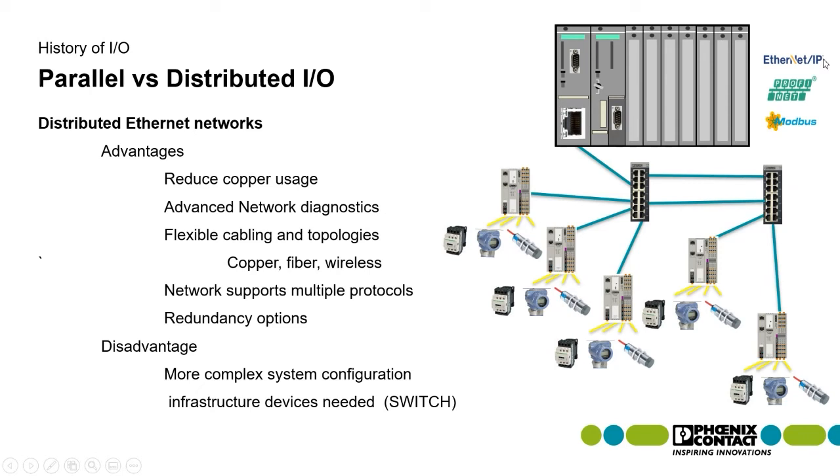One point I want to double down on: while all three of these, Modbus, Profinet, and Ethernet IP, are Ethernet and run on the Ethernet concept, they all have recommendations. Modbus has no real recommendation. They don't care what you use or what functions your switches and network support. Ethernet IP asks that your switches support specific functionalities, like multicast communications, certain levels of redundancy, port mirroring, quality control, and VLANs.